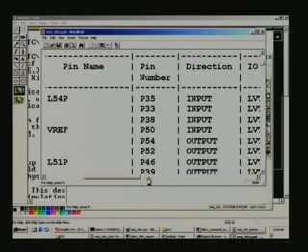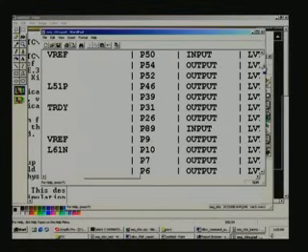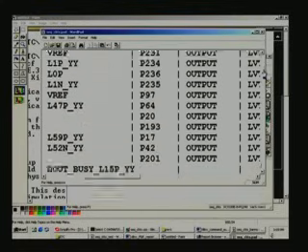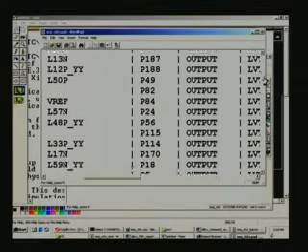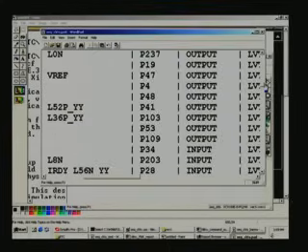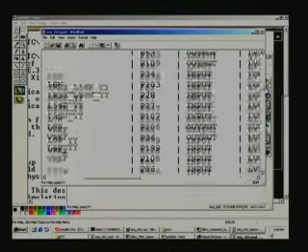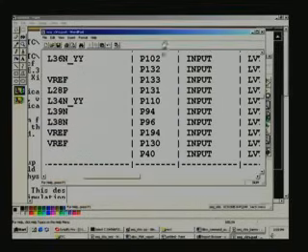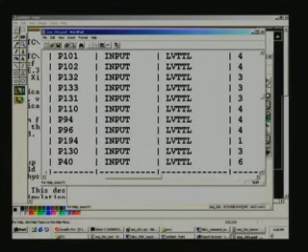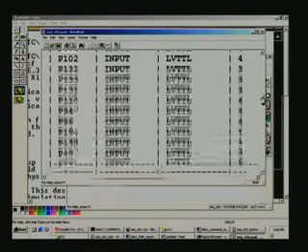So pin 35, maybe there may be some rows, because it is only 240 pin, probably it is merely some deep type, or I do not remember really, and you can see some 237 pin number coming. So it is a 240 pin package. So naturally you should not see anything greater than 240 here, and each of these signals, whether it is an input or not, whether it is TTL compatible or let us see,